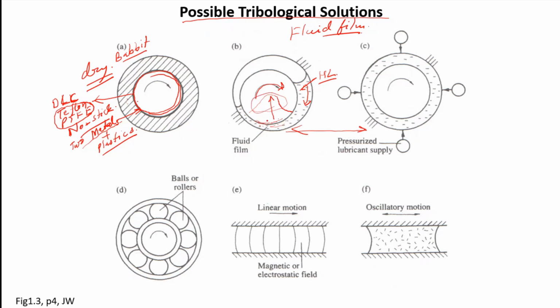this one, the mean pressure will all act in this direction, and your shaft is supporting some load, right? The shaft will always have some load. So the load is from this. This pressure will actually cause this force in this direction, which will carry the load. So this hydrodynamic pressure is enough to carry the load, and this is what happens in this kind of lubrication.